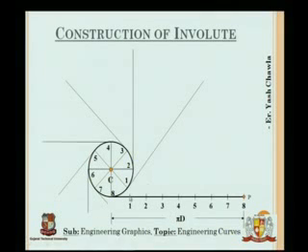What I'll do is take my point 1, and the length would be 1 to 8. What I have assumed is that the distance between 8 and 1 has already been wound on the string when it reaches 1, right? That's why I'll take 1 and 8 with my center as 1. I'll cut an arc on this line that will show me the end point P which has remained.